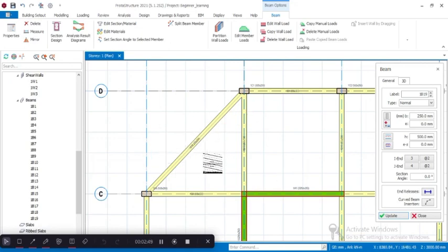Click the beam icon and place the cursor on the edge of the primary beam, when you want to place a beam on another beam. Notice the snap points 0.25L, 0.33L, 0.5L, 0.67L, and 0.75L will be shown when the cursor is placed on the beam.